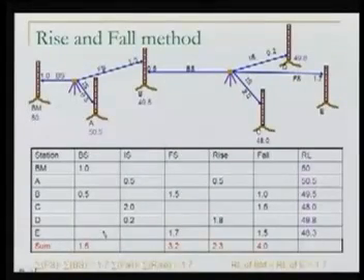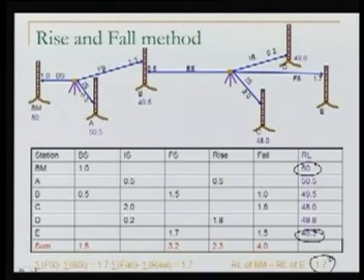Well, the very first check is RL of first point minus RL of last point is 1.7. Okay. Well, we have already done sigma of backside minus sigma of foresight. This is 1.7. We have done it already. One more check that we can do, because we are either rising up or falling down.